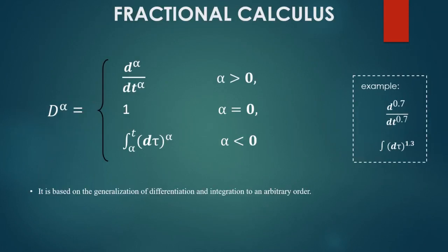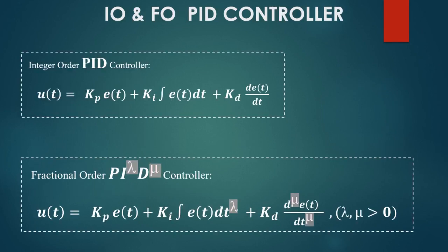So what is meant by fractional calculus? In simple terms, it is the generalization of the differentiation and integration terms to an arbitrary order. A conventional PID controller has one integral term and one derivative term. If we raise these integral and derivative terms to an arbitrary order, we come up with a fractional order PID controller. And that is what we would be exploring in this research work.